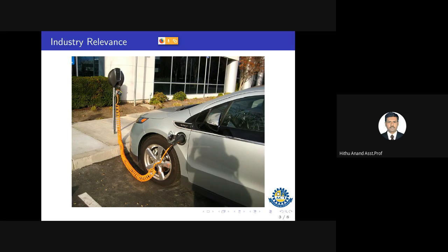Once you have the characteristics, you must see what the highest power requirement is, and you have to decide the capacity of the motor based on that. But you cannot simply buy a motor for the highest capacity, because that is needed only for some duration.